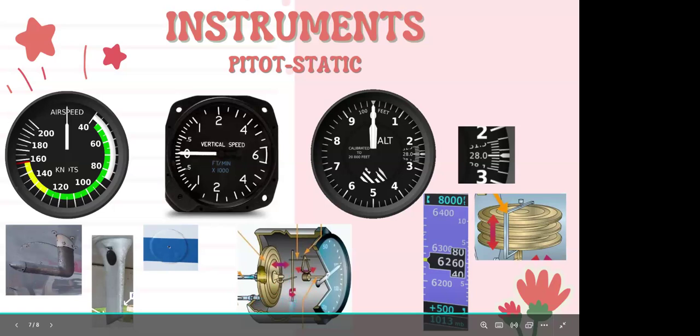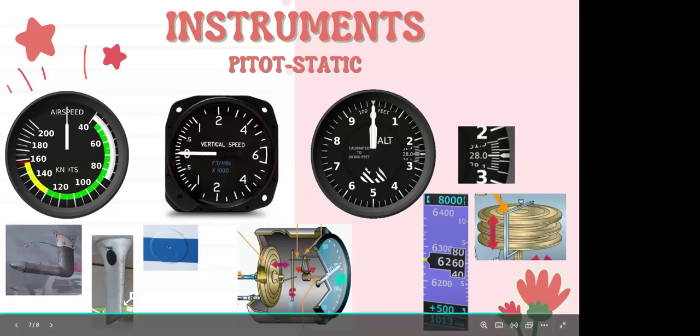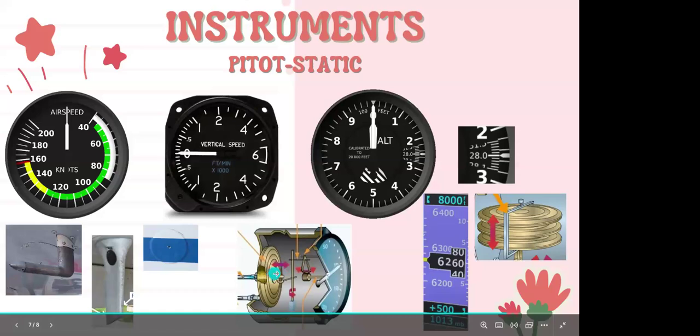So we have our dynamic air, the speed moving through the air, and the static air. As you said earlier, when you go up in altitude, the air gets thinner. And what that does is cause fewer air molecules to be inside of the case. That causes less pressure on the diaphragm, which causes it to expand.